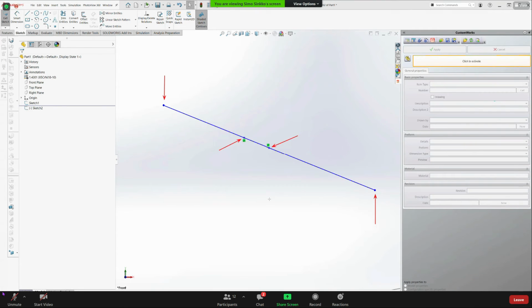And now, based on this free body diagram, you are able to calculate how big this cylinder force should be so that it can lift the F that is in here. We still have here F divided by 4, and we have here B, which is equal to F divided by 4.